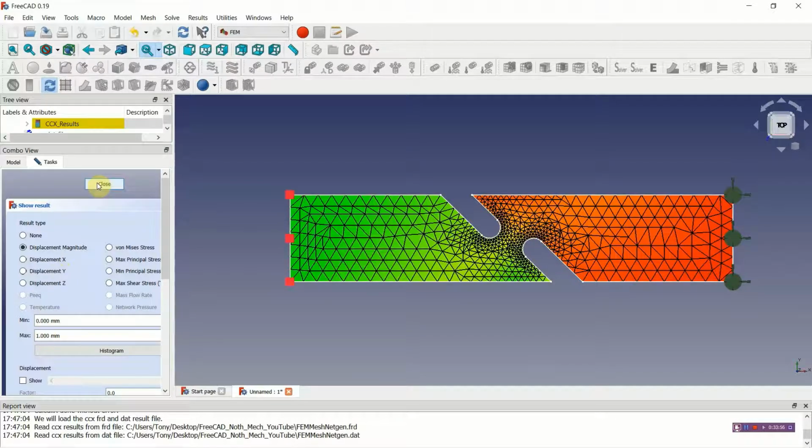I'll close that. We can also do maximum principal stress or von Mises stress. Von Mises stress is not only for an elasto-plastic analysis. This is just a quantity of stresses. I did go through it in lecture 6. We can plot that if we wanted to, and you can start to see in here and here high stress concentrations. The same if we look at maximum principal stresses, you can see the values in here.